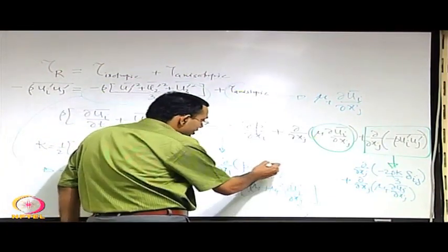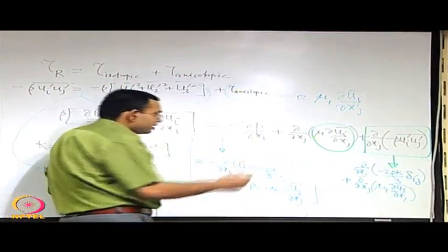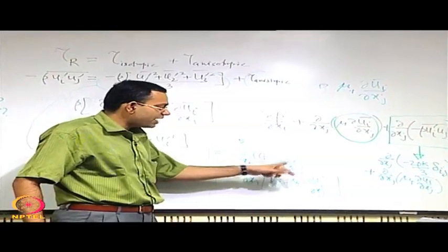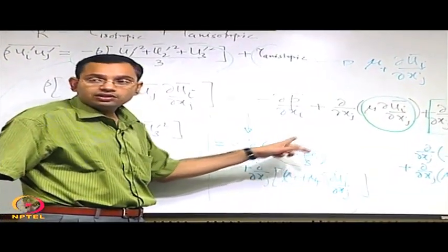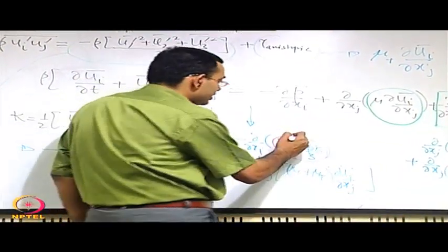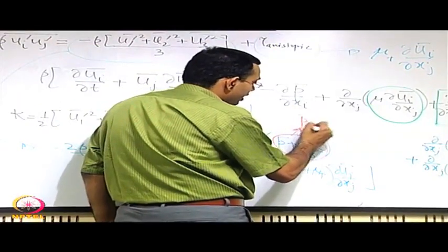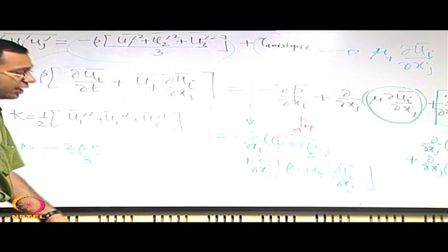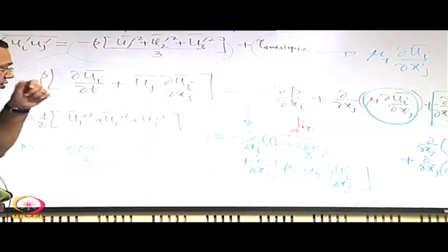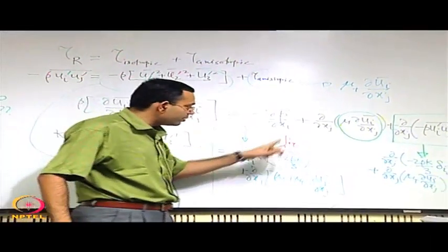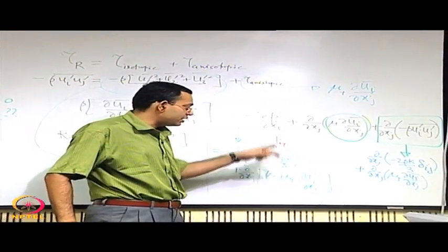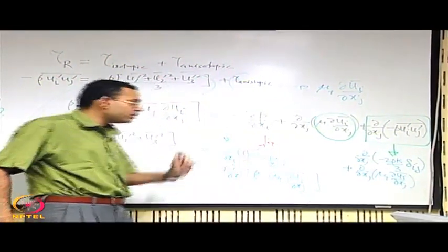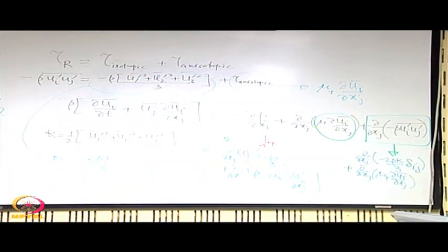What are the important changes? One important change is, instead of the pressure you have the average pressure plus a term dependent on the turbulent kinetic energy, and let us say we call it P average equivalent. So, if we are solving it in the same form as that of the Navier Stokes equation, no problem, but whatever P we get, we have to understand that it is not P average, but an equivalent with some term because of the kinetic energy.